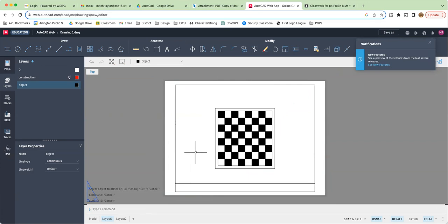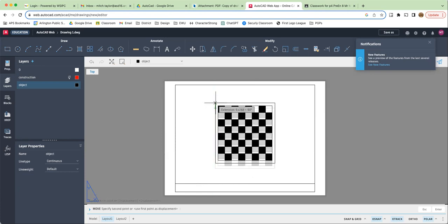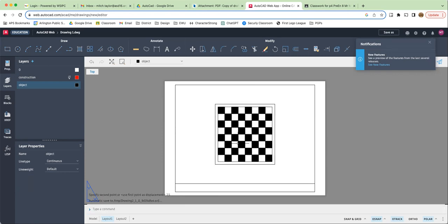Now, one of the things that we can do at this point, because this is now no longer in the center of our drawing space, let's select this whole thing. We will type in move as our command. We will specify a base point. How about here? Let's pull this straight up, 7.5. We made the title block at the bottom 15, and therefore this is 15 closer from there to there than it was there to there. We need to split the difference, so we moved it 7.5.